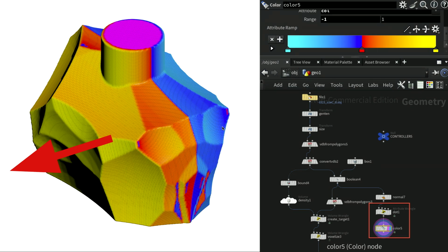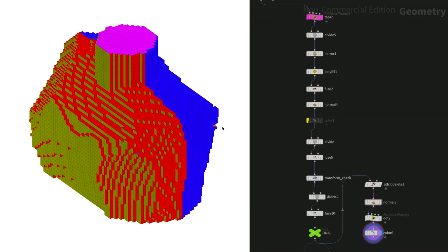So as a result, the final object was designed to be symmetrical in the end, so that you'll have a straight line in the middle, which made creating and using the mold much easier. While we experimented with different seam line placements, asymmetrical designs made the molding process significantly more complex. So this choice to prioritize symmetry was aligned with physical molding limitations and practical considerations. And then we did the same analysis for the converted voxel shape to make sure that everything is okay.